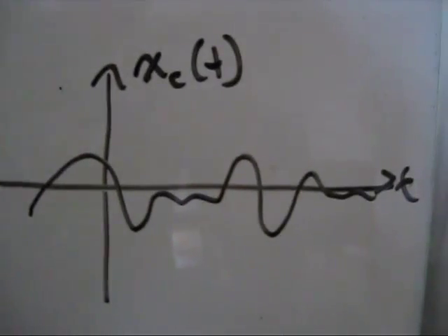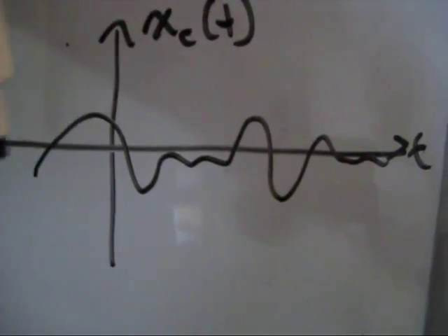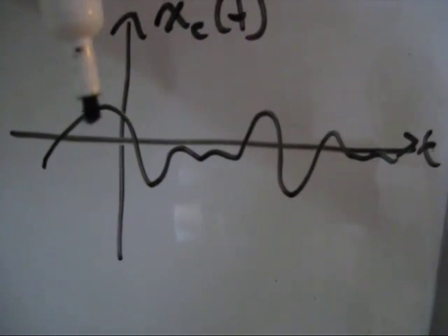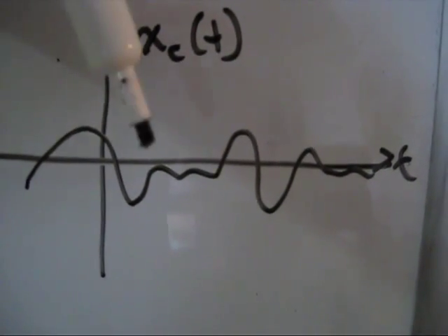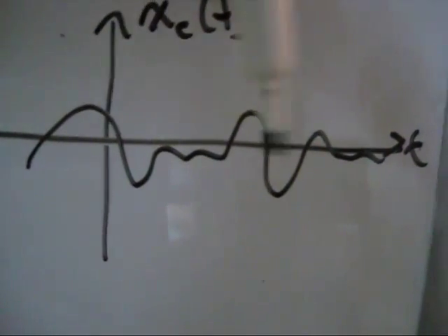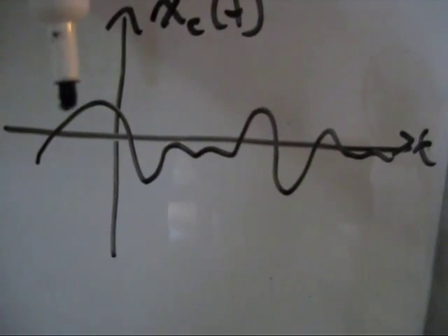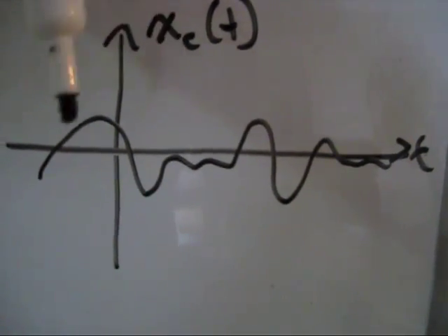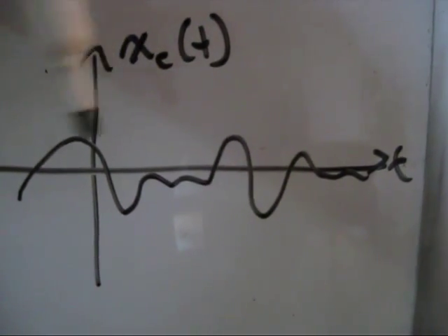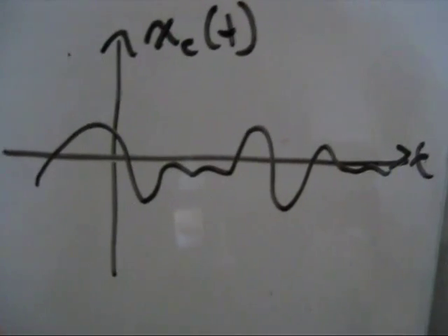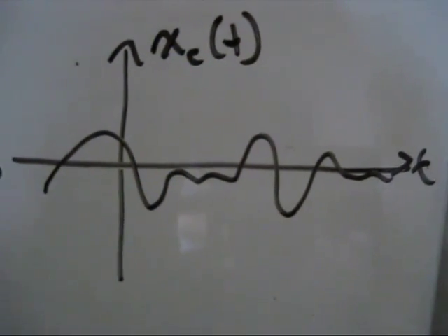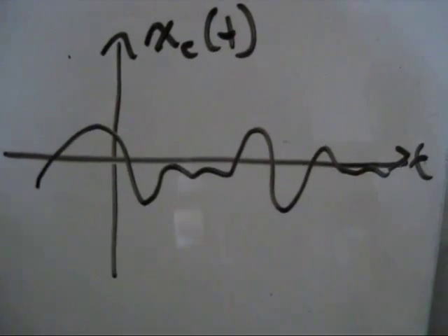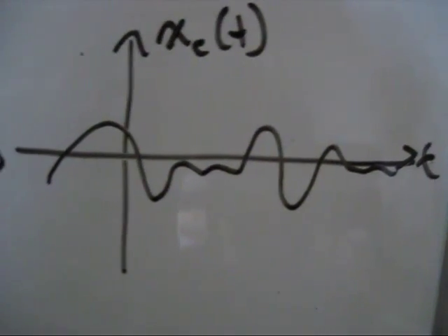So what we're going to do is go over to the whiteboard, get right into it, and I'm going to show you guys what I'm talking about. Alright, let's get right into it, shall we? When you have some sort of signal that you want to sample, that signal is made up of at least one, usually many, frequency components that you then want to accurately put into your sampled version of the signal. You don't want to lose any of those frequency components because then you're losing information about the signal. But today we're going to look at a very special case where you can actually sample at less than 2 times the maximum frequency of the signal.